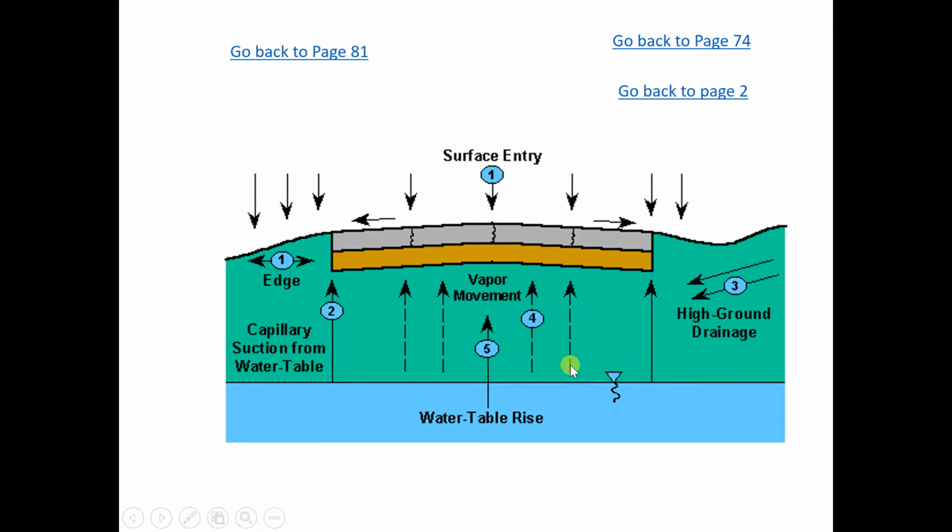The main aim is to keep the pavement dry, both the pavement materials as well as the subgrade, which is just at the formation level. That's the part that we need to compact properly before receiving the pavement materials: the sub-base, the base course, and the wearing course.